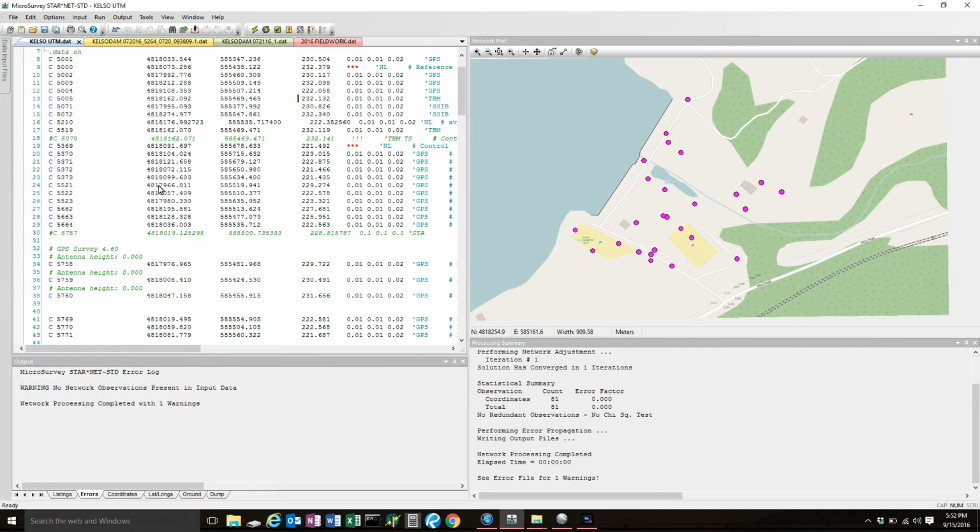In this data file, the first part of it contains a bunch of GPS observations. These are all RTK shots that we're taking either for resection points or on, here's a couple SSIPs, that's a survey monument or a nail. And my current adjustment, which I just ran, shows the various GPS points.